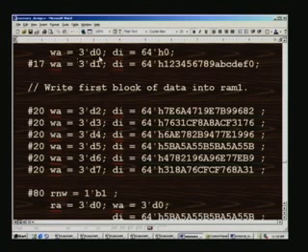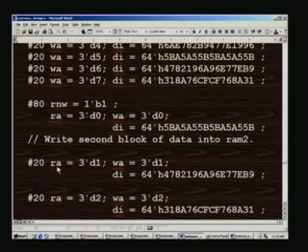And for each time there are 0 through 7 locations, that is what is mentioned here, and because it is 50 megahertz operation, we have made it change every 20 nanoseconds, and staggering is done just to offset as we have seen before. And next time we write the next block. So now we will write it into RAM 2, and a different block of data is being written, and note the difference here. While we are writing, this is write for RAM 2, we are also reading simultaneously from RAM 1, that is the implication there.